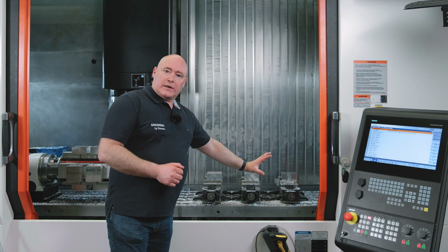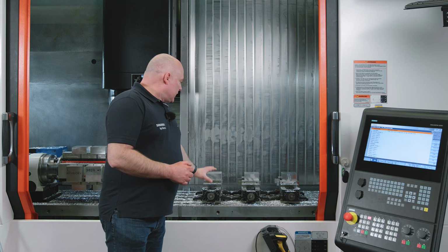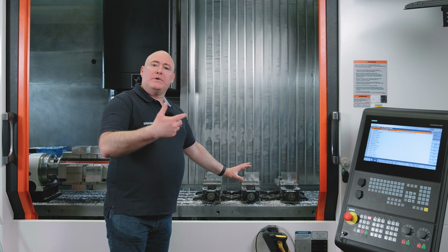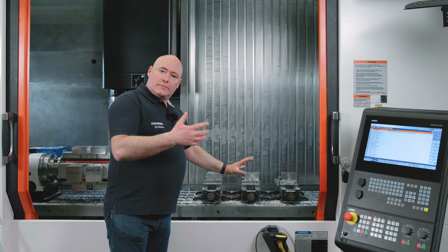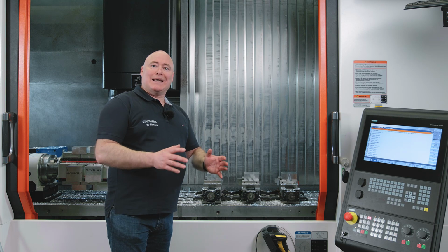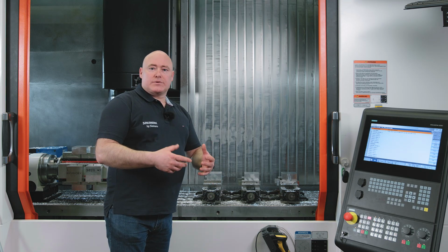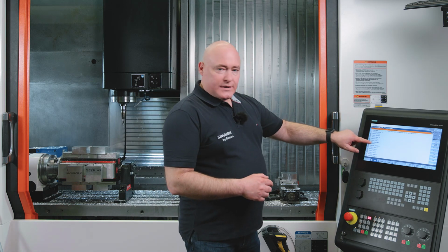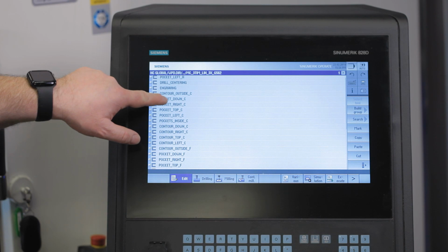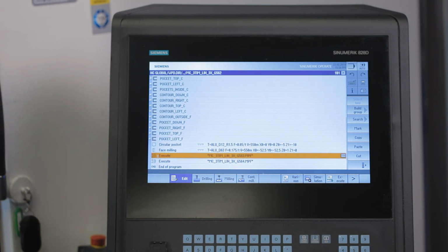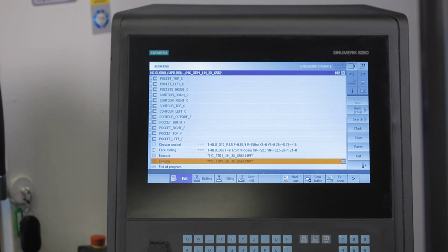Let's start with a purely linear clamping without the software functionality for multi-clamping optimization. Later, we'll repeat the process with the software functionality, which will help us see the differences with regard to machining, shorter machining times and so on, very clearly. Here is the program for this component. In it, the individual operations are processed one by one, and the 2 other programs are then called for the 2nd or 3rd clamping.